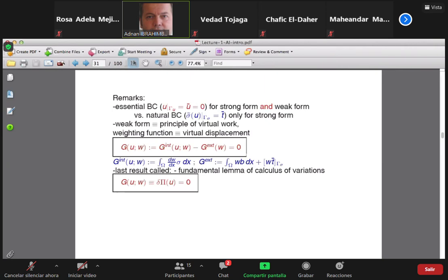On the other hand, you have a contribution of the external loads. This is the distributed load b times dx times the corresponding displacement W at a particular point x. You integrate from 0 to L. And on top of that, you have the contribution of the applied traction on the boundary gamma sigma, which is what I discussed for the value of x equal to L. So if these two values match, that means you have an equilibrium. So basically, then you can say that the internal and external forces are matching.